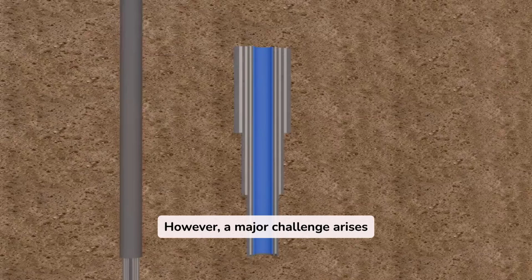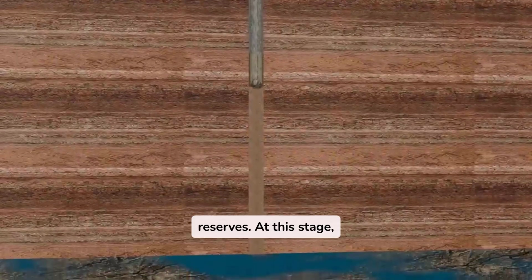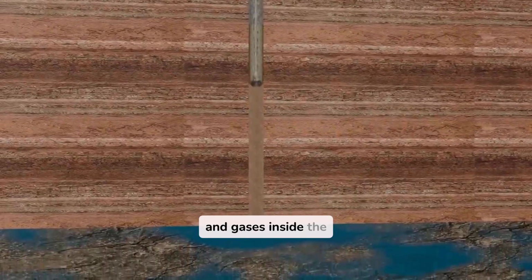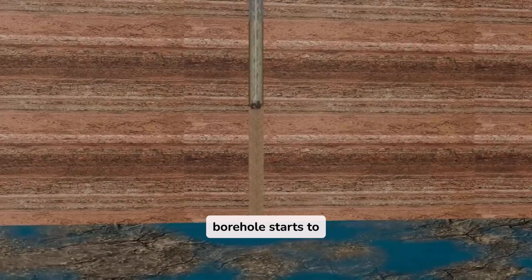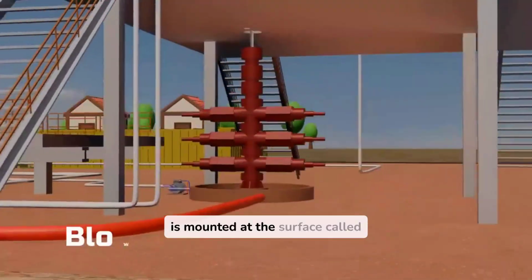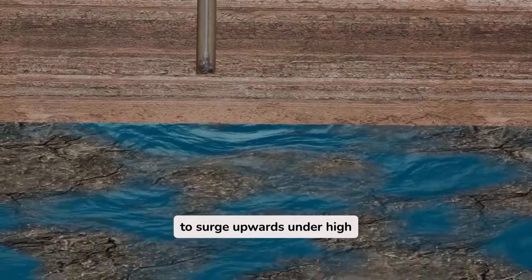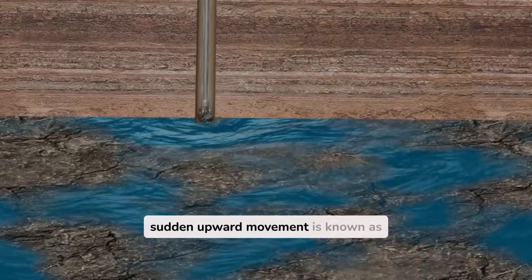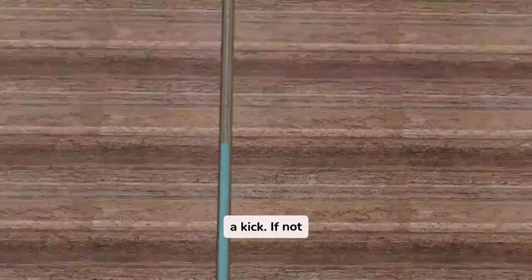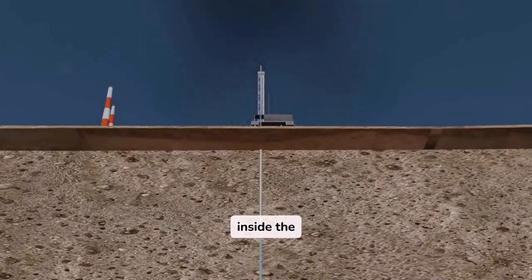However, a major challenge arises when the drill bit reaches close to the oil reserves. At this stage, the pressure from the oil and gases inside the borehole starts to increase significantly. After installing the surface casing, a very important safety device is mounted at the surface called the blowout preventer, or BOP. Oil often tries to surge upwards under high pressure. This sudden upward movement is known as a kick. If not controlled, a kick can lead to a dangerous blowout inside the oil rig.